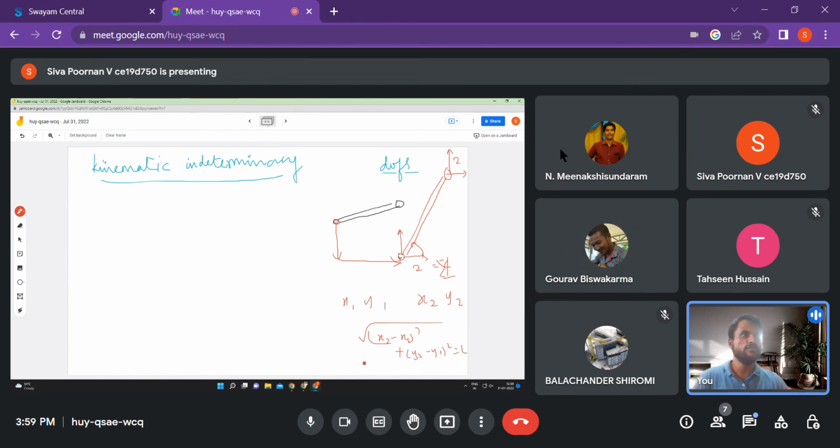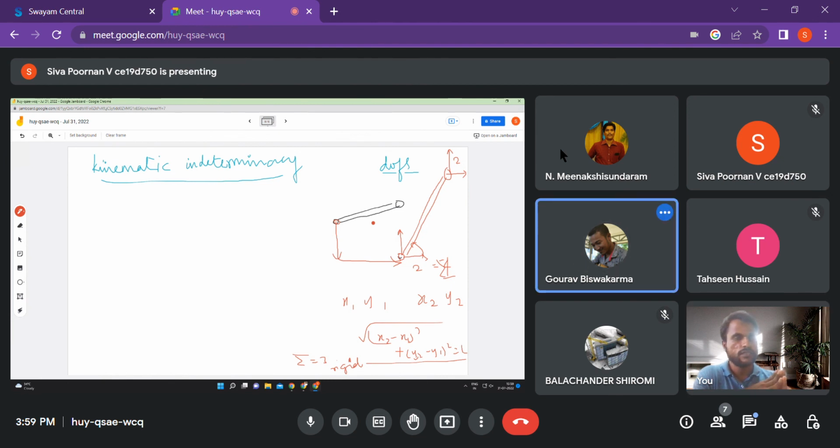So that is how we have eliminated 1 degree of freedom, and total degree of freedom will become 3 if it were rigid. Okay, good. Then this is about trusses. For trusses, you can just take every point has 2 degrees of freedom for a planar truss. If you have a space truss, you have to take 3. Okay. Now, if you go to beam, every point will have, in addition to 2 translational degrees of freedom, a rotation, right?